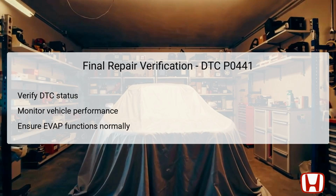After completing the necessary repairs and troubleshooting for DTC P0441, the final step is to verify the repair's effectiveness. First, recheck the DTC status using the HDS. There should be no recurrence of the initial DTC or any associated codes. Monitoring the vehicle's performance is also critical following repairs. Observe whether the check engine light remains off and if the vehicle operates smoothly.